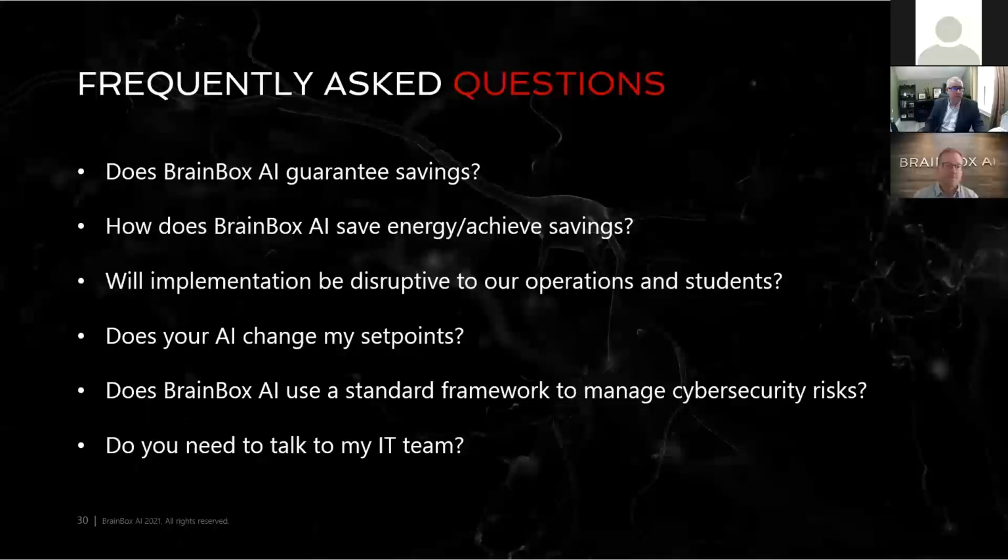Next question, does the artificial intelligence change my set points? It's a great question. So we do not change space temperature set points. We leave that up to the customer. So if the customer wants 72 degrees with a 2 degree on each side deadband, by all means do that. If they want 70, do that. What the BrainBox does is they change how the HVAC system achieves that set point.